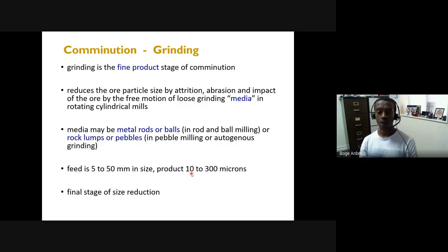So I'll probably say, why don't you use maybe a ball mill followed by an ultra-fine grinding circuit? Okay, so usually, although we say grinding mills work well below 100 microns, the limitation usually is below about 70 or 80 microns. They don't perform well. And in fact, studies have shown that of all the power we use during comminution or during crushing and grinding, only 1 or 2% is actually used for breakage. All the other energy is lost as heat, and that is a problem. And that is usually to do with not finding the best final product size for the grinding mill.